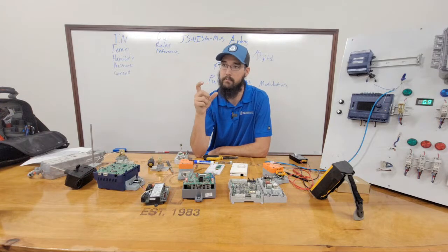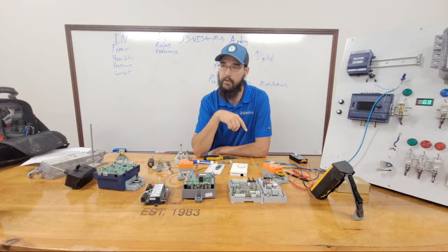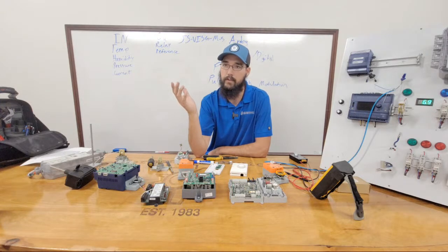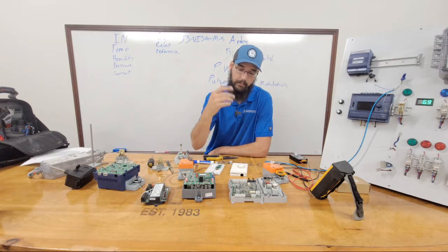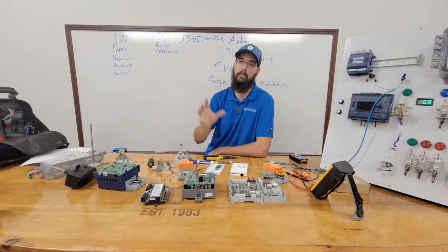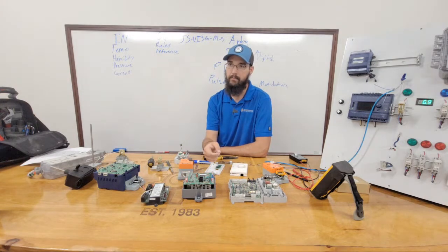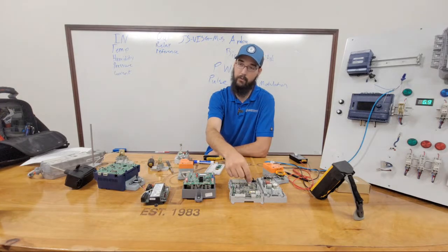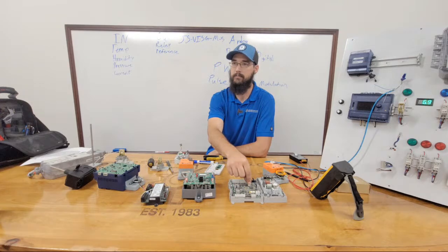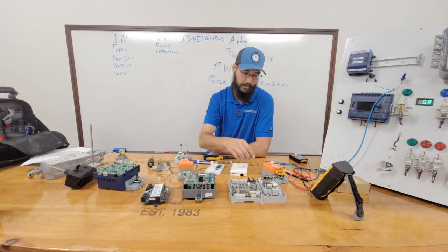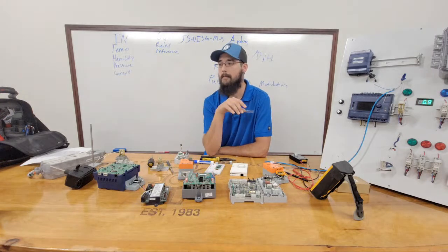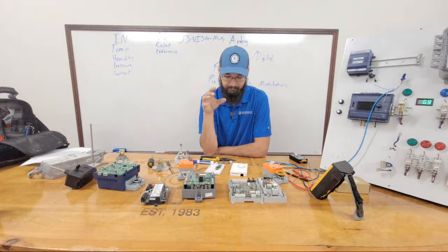You can just go into the logic blocks and reassign that output terminal, and then just move your reference wire over, and you're golden. You don't need to replace it, and you can put something in there or make a note in the controls, whatever. There's things you could do to notate that output 3 is bad without having to spend $1,000 or thousands of dollars to change a controller out, and all the time and pain in the butt headache that is. Yeah, anyway.